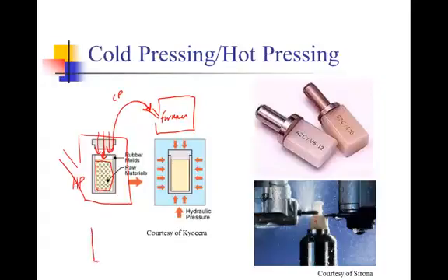And the problem with using uniaxial pressing is that afterwards in your product there is a gradient of packing densities, and the parts that have more porosity left in them will shrink more upon sintering than the parts that have a little bit of porosity left in them, and that will cause the part to warp and it won't fit wherever you want to put it afterwards.